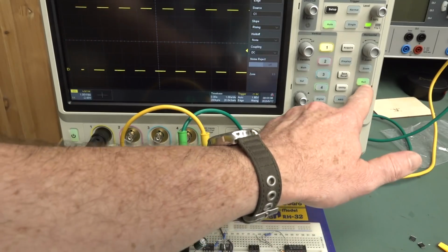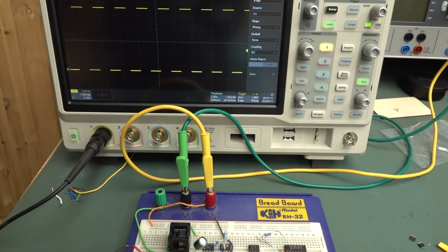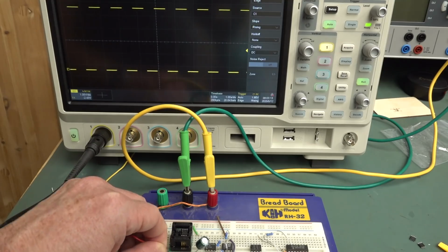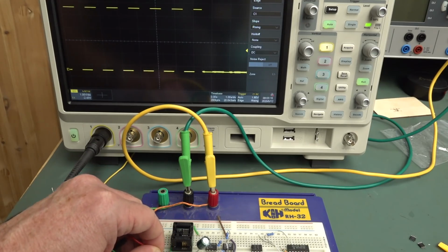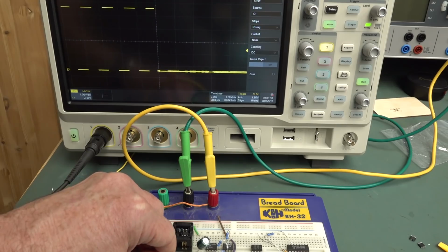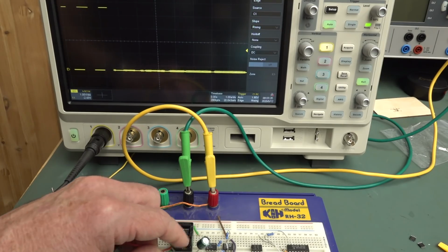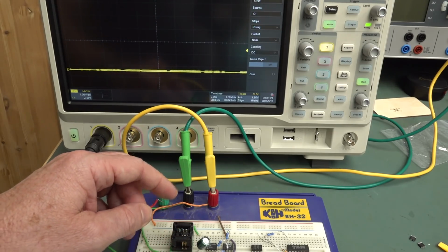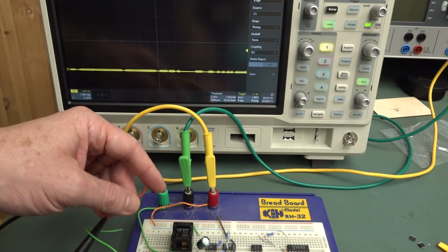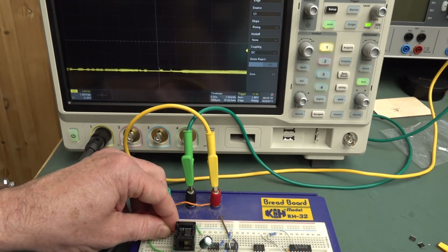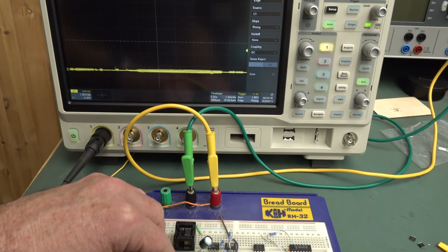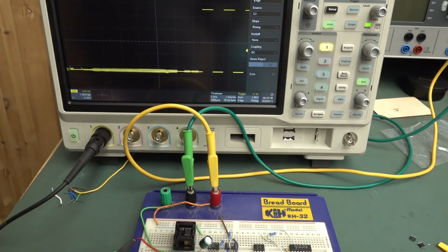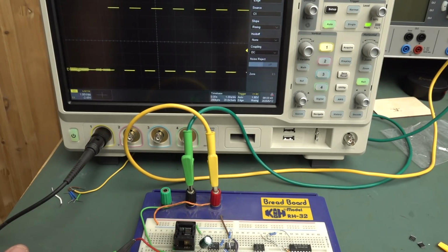Anyway, there you go. Dumbass Dave didn't see the roll button over here. There you go. So that's our output, and if we probe the other pins, you can see we get nothing, because that's actually not an output, so we're picking up noise there. If I touch that, we're picking up my 50 hertz. So they're configured as inputs, not as outputs. Only pin 7 there is configured as the output. So we're getting our 1 hertz signal, and that comes from an internal timer-based interrupt divided by the main internal clock. Fantastic. So there you go.